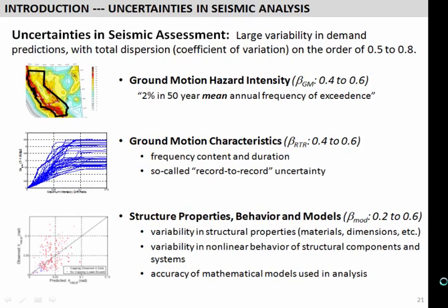Now I did want to bring up, you see in those slides that I just showed, there's variability in our output. One of the things in doing these nonlinear dynamic analyses, it's kind of unsettling because it looks like there's more uncertainty in our designs than there ever was. But the fact is that uncertainty has always been there. And you can think about, we're checking things at MCE level ground motions, let's say. There's uncertainties in even how we define that MCE. When you look at the hazard functions, they're mean annual frequencies. So there's uncertainty about that mean of just what the MCE level intensity of ground shaking is.